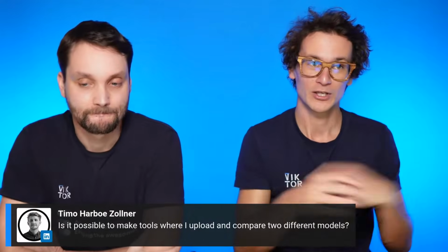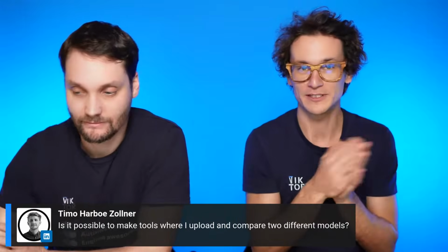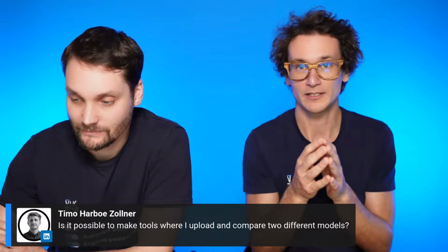What you can do is, for example, you have different design stages: a preliminary design stage, a developed design stage, a detailed design stage, and you sometimes want to check if you derailed at some point from your design. And what you could do is upload multiple ETABS models as a file upload field. Previously, we were uploading an Excel file, but you can upload an ETABS file and then send it to ETABS, retrieve the results back from multiple files and then compare those results. That's a really good example that you've raised just now. I like it.